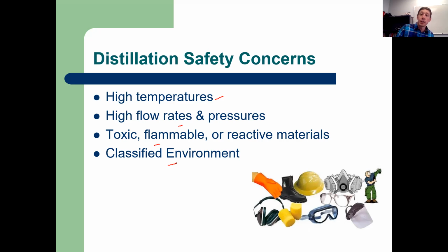And so if we have gasoline or alcohol vapors or any volatile vapors in there, then if we have an open spark, we have the potential for a fire or a combustion hazard. So distillation is almost always in a classified environment. And so that's why, when we went to the lab, it's in that concrete enclosure separated off from the rest of the processing facility.